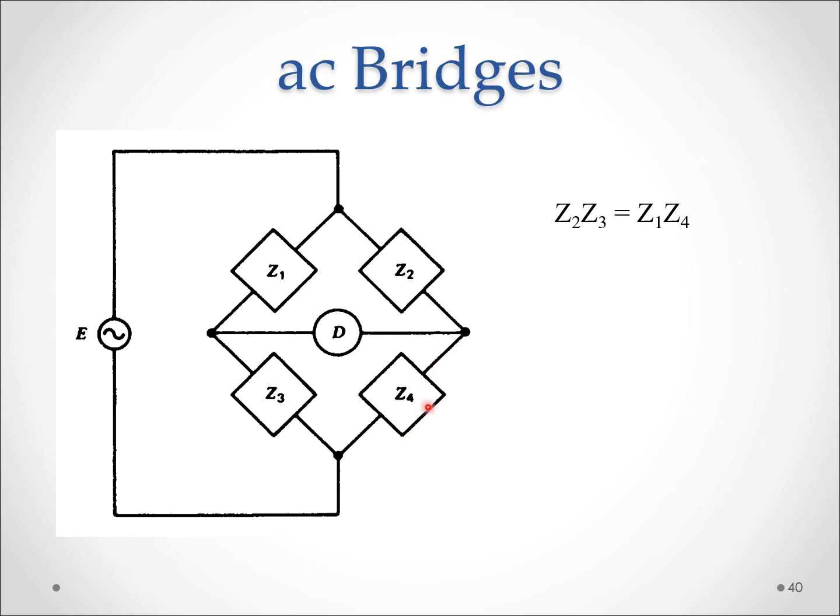In the last lecture, we explored bridge circuits. They work by creating two voltage dividers using resistors and a null detector, like a voltmeter, to help us find the balance point when the voltage across it is zero. Today, we will delve deeper into a specific type, the AC bridge.